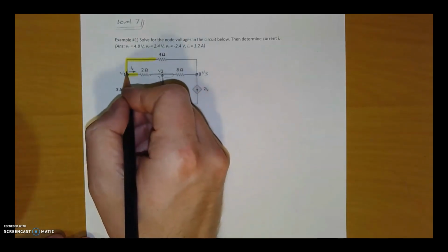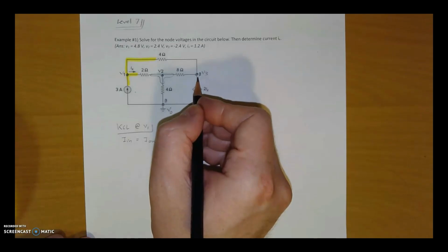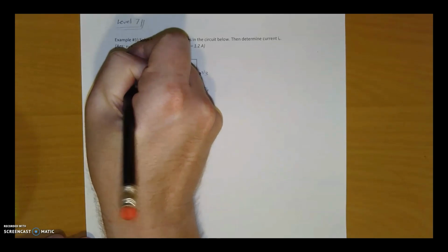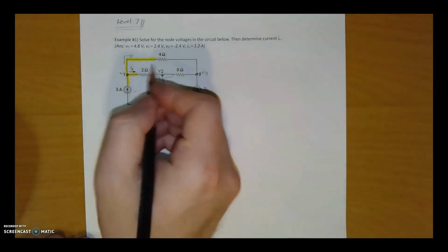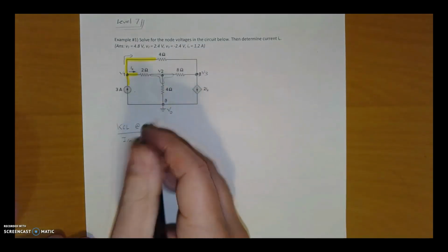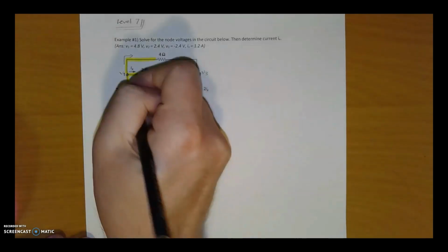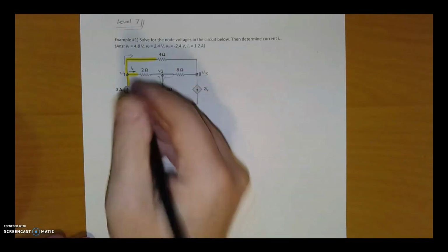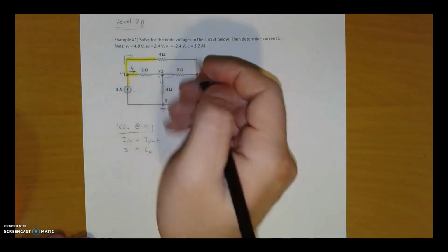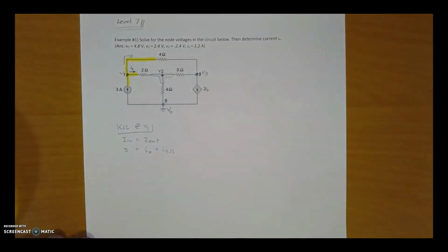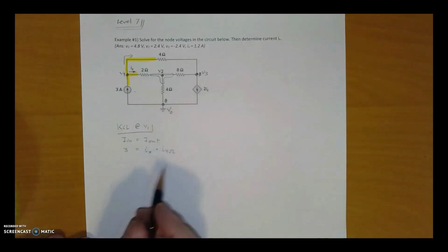And this one I can do whatever I want with. The current through this 4 ohm over to V3 is up to me. For the time being, I'm just going to assume that it leaves. It doesn't really matter. You get to choose, and as long as you follow passive sign convention with your polarities, you'll be fine. In this case, we have 3 amps entering. And leaving, I have Ix, and I have this current here, which for the time being, I'm going to call I through the 4 ohm. But as we do more of these, you're going to see I'm just going to jump straight to a different substitution for these.